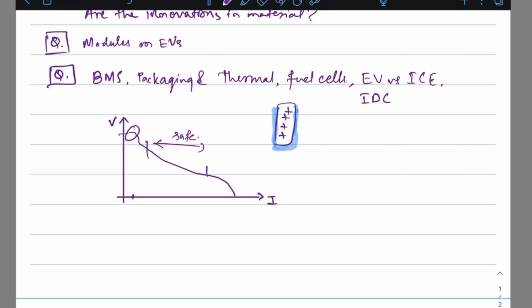As I was saying, the driving cycle would help you in taking care of the consumption and gear shifts. A driving cycle will have braking phases and acceleration phases at different levels, to different speeds. If you run the driving cycle again and again repeatedly, you will get a good picture of what is going to happen in a real-world scenario. So that is a rough-cut understanding of the driving cycle. Okay, yes, Vivek, you had a question. Thank you.